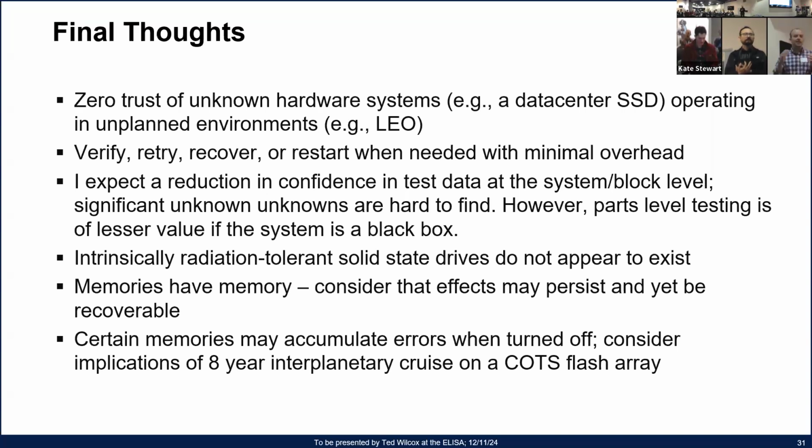If you're taking a robust process that has MRAM available and you're designing your own system, you can build a very robust memory chip doing that. If you are capitalizing on a commercial memory that uses one of these non-charge based memory architectures, and it wasn't designed for radiation tolerance in all of that peripheral circuitry, it's as hit or miss as any other technology.